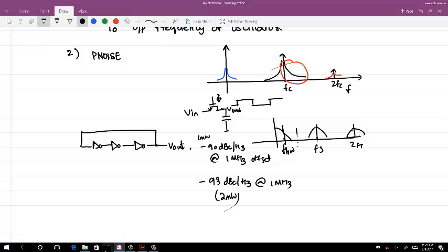Okay, and then I find that if this number is working well for me, I come back to the schematic and I want to increase the power, and I do not want to change any output frequency or anything. I want just phase noise to scale very nicely. So if in one case my phase noise was this, I just want it to reduce by 3 dB everywhere. I want this transition. So what kind of scaling can you think about? Without changing the noise profile, it's just scaling by 3 dB down. What can I do to the new circuit or in the schematic?